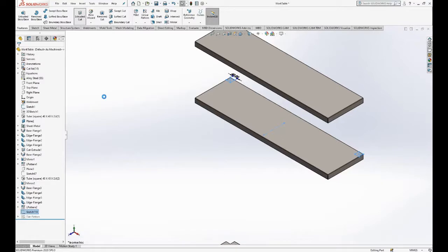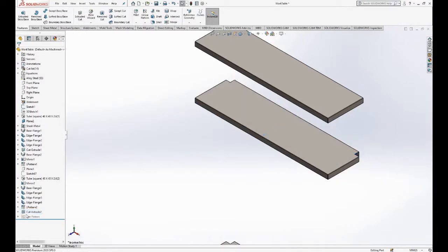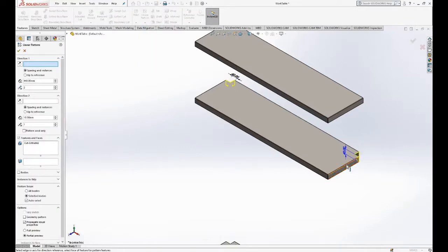And we'll go through the same exercise. So I'm going to double click on the, well, before I do that, I've got to go back to the add edit models. I want to select on the leg, just double click it, and this is the dialog I need to be into. So I'm going to go to the, let's try the upper layout. Oops, it's going to be the lower layout, and it's the 3000 dimension, so that's the overall height. So again, it's grabbing that. We'll go ahead and label that as leg height. Add that.